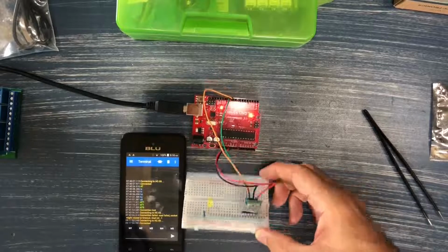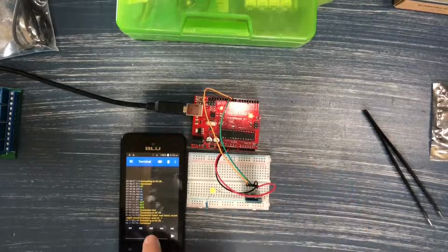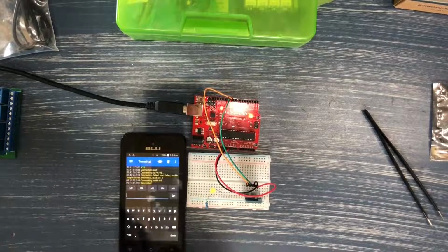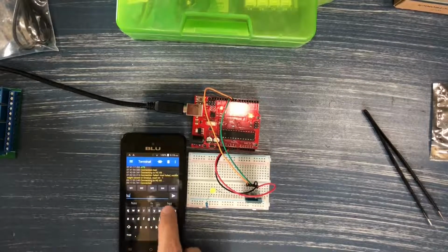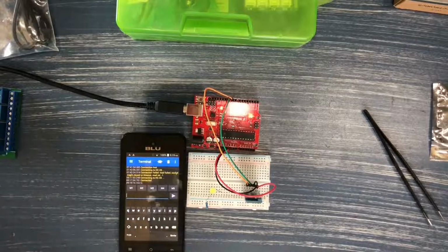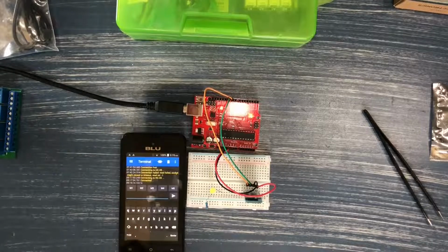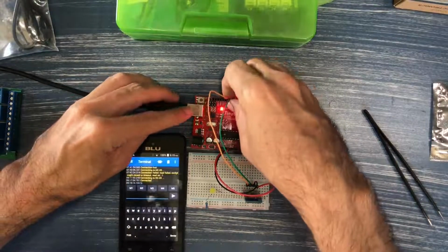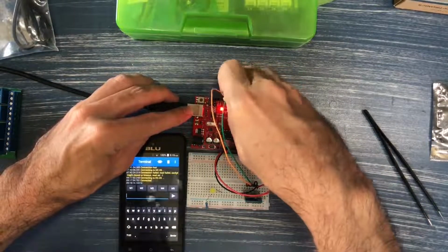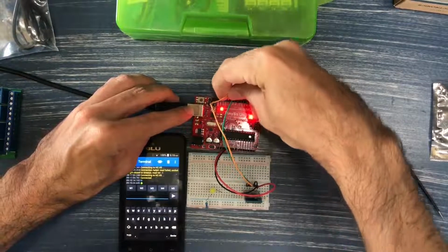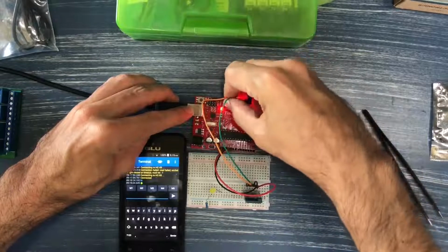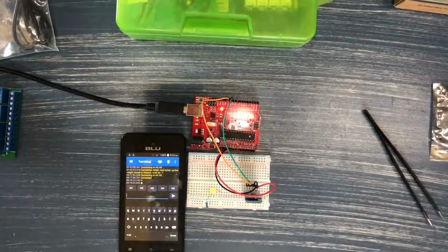Okay, which means that it is paired with another device and connected, and on the screen of the phone we can see that it is connected as well. Okay, so they seem to be connected. Let's see if we can send and receive. So I sent the word hi to the Arduino. The cables seem to be the other way around. Sorry about that. That's why I put up that slide where it's important to always keep in mind that the RX and the TX switch around from module to microcontroller.